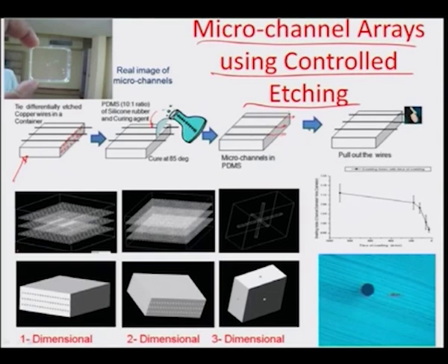So, you can have microchannels not only on a surface by using 2.5D lithography, but also in the bulk or the volume, as you can see in some of these illustrations, where you can see how the channels have been created. If you look at this particular figure closely, you will see a crisscross channel created within the volume of the block. There is one channel in this direction, there is another channel in this direction, if you look at it very, very closely.